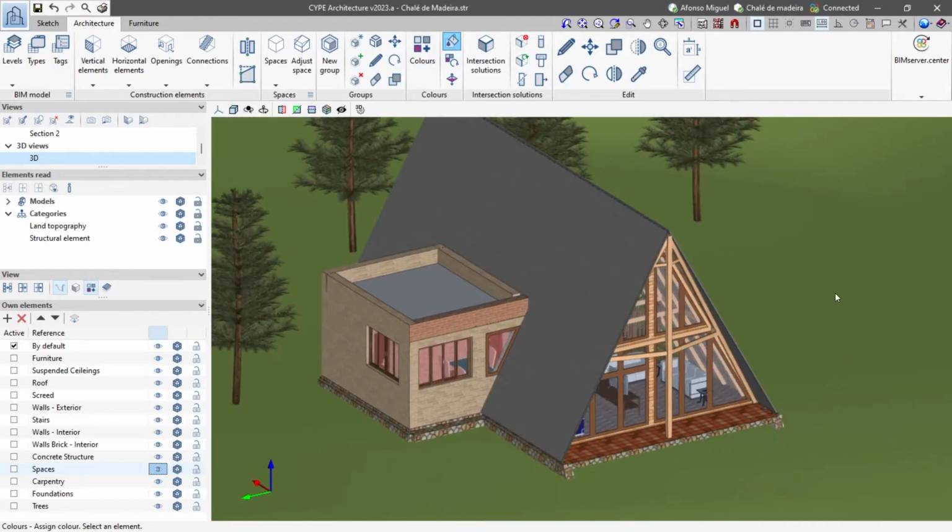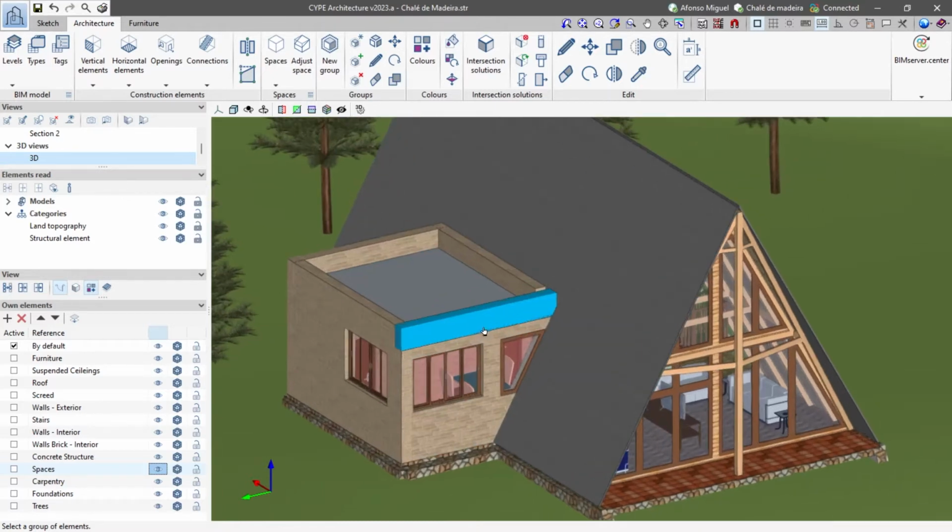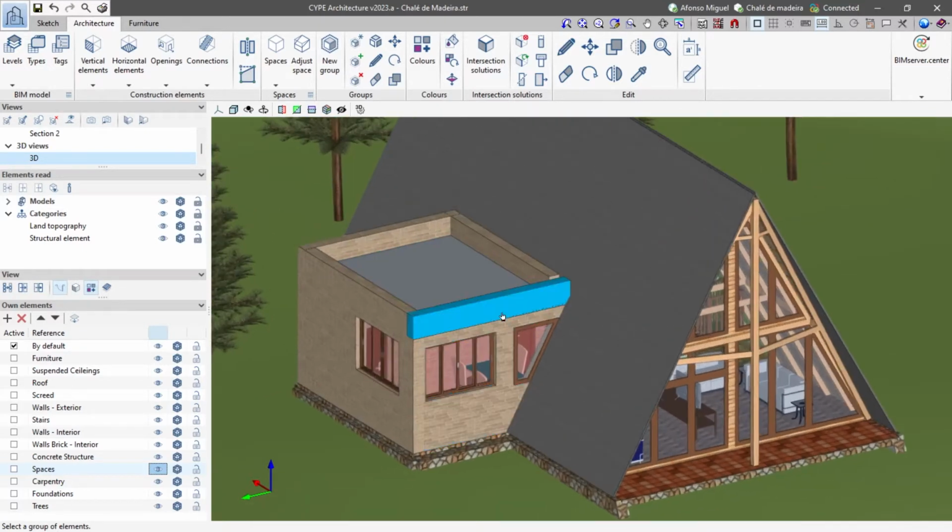This is, as I said before, a manual way to add something. Of course, you can add this color to a group of content, for example, selecting different contents. But this color is not connected to the system of your model. What it means is, if you must change this color now, and if you had added this color to different points of your model, you must add one by one, point by point, clicking and editing the content.